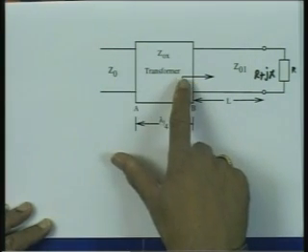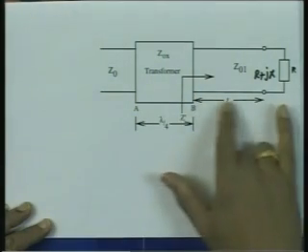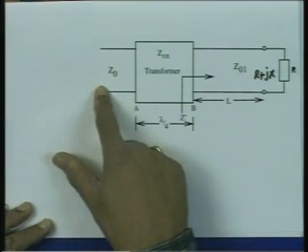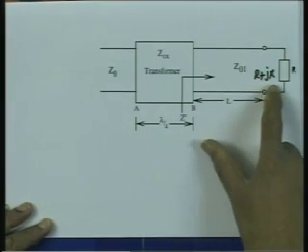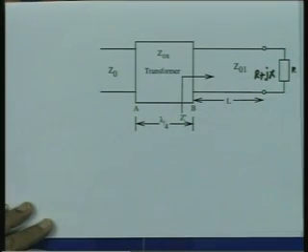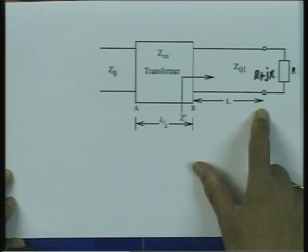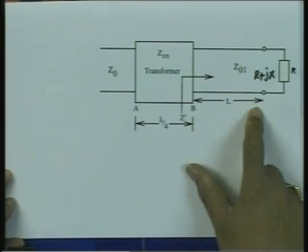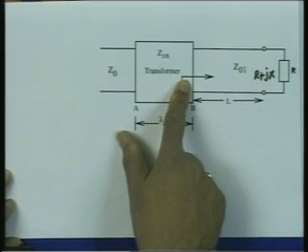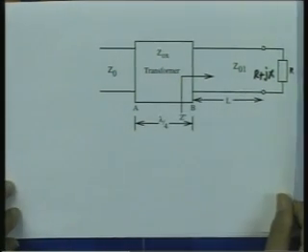However, to make the impedance real at this point, I introduce a section of a transmission line which has some characteristic impedance Z01, it could as well be Z0, and transform this impedance R plus jX to a value which is a real value. So, there are two things. One is what should be the length of this line, and what is the value of the impedance which you see at this location. This we can do again very simply by using the Smith chart.